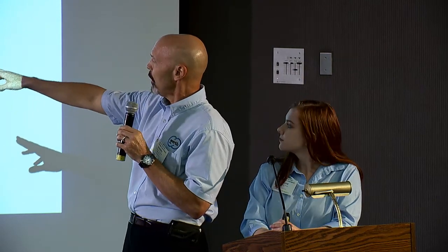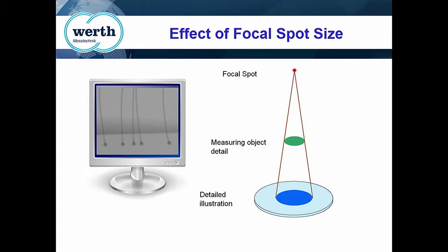So it's cone beam tomography. All tomography machines work on a cone beam. There are linear arrays, which in a perfect world would be a great way to take a picture straight on, and you get your best focus, less deflection of the photons going through the part. But that would take a very, very long time to X-ray anything. So we use a cone beam. It's like putting a flashlight up, and you get a nice tight spot right in the middle where you want to shine, and then over to the sides, you get the cone beam artifact. You get a little bit of blurriness off to the side.